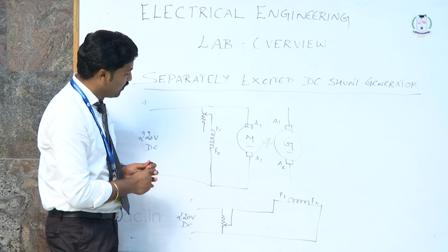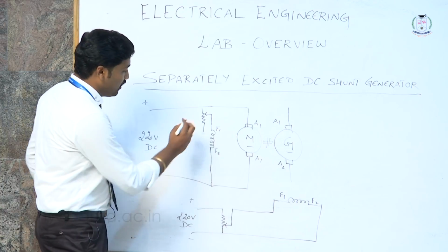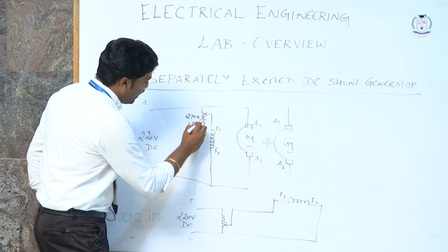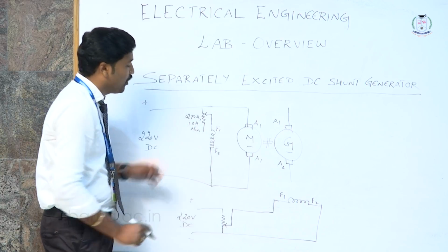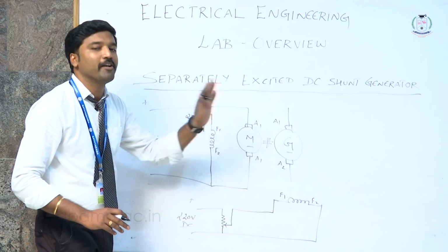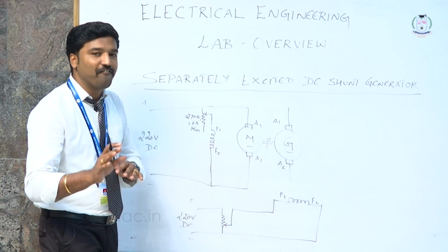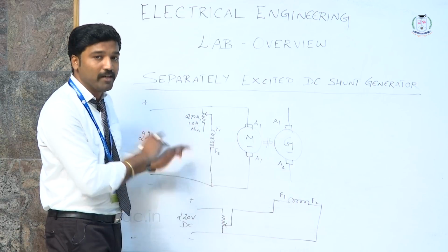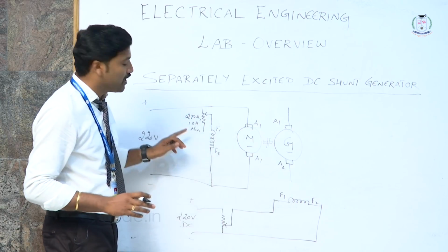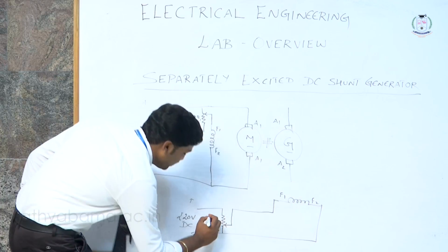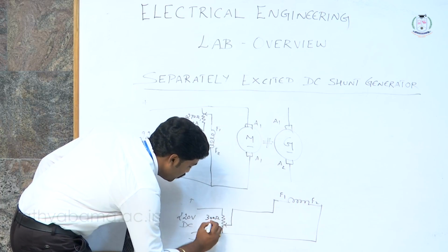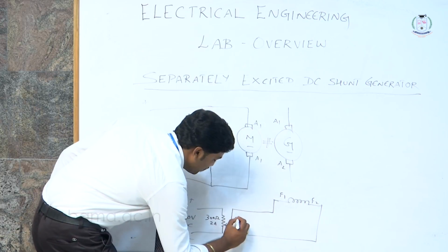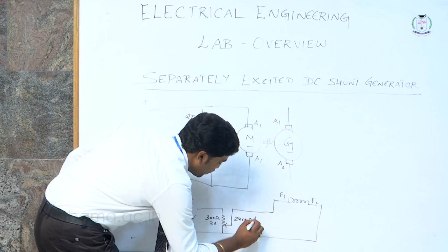So the rheostat and field, everything is ready. I will just complete the values of the rheostat as well. 270 ohm, 1.2 amps and minimum. The word minimum for your motor rheostat is quite common in all your experiments. Any motor field rheostat should always be at minimum. This idea is not only applicable for this experiment; in any experiment, the motor rheostat should always be at minimum. If you take this one, 300 ohm, 2 amps, this is at maximum position, but this rheostat is particularly called the zero output voltage rheostat.